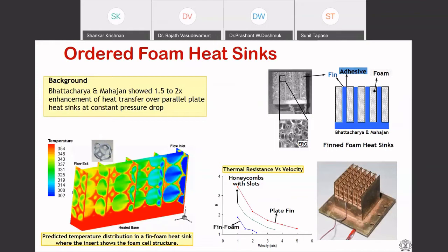Investment casting is very challenging because traditional investment casting methods allow you to have only feature sizes that are 2 mm or above. Some of these feature sizes can be as small as 0.4, 0.5 mm. We were still able to do it by investment casting of our 3D printed part, and we successfully demonstrated this technology. This is almost 10 years old now. Anyway, that's that work.